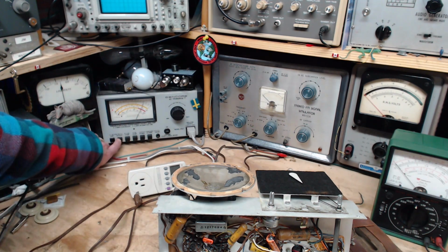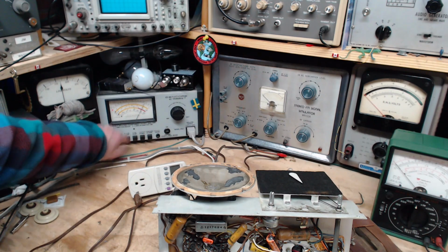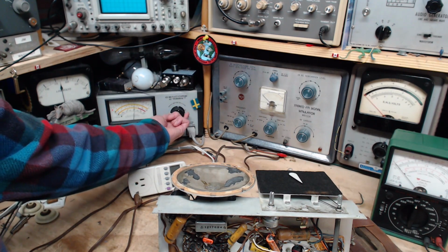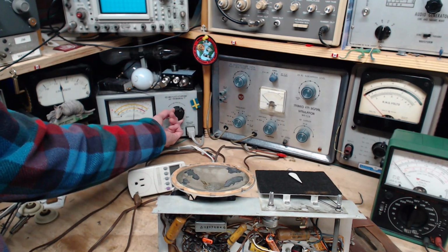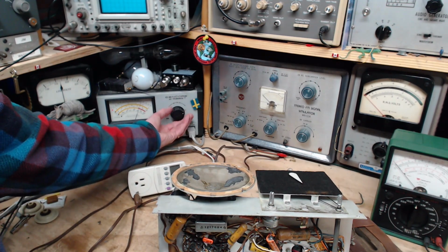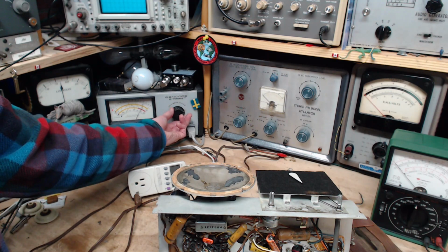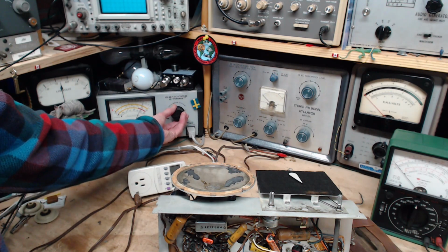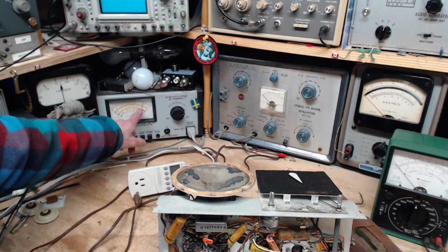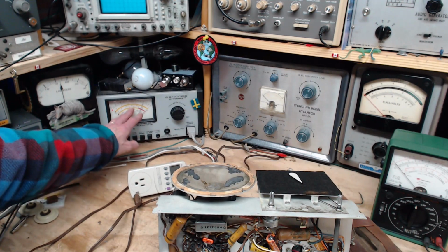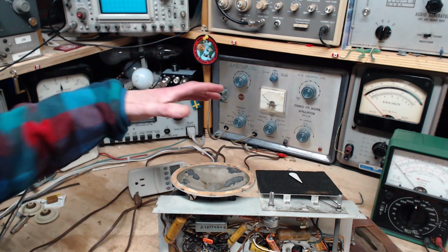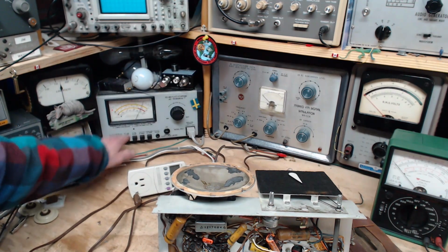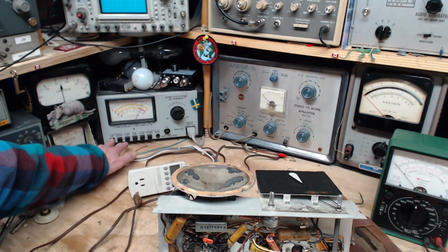Here, this is the output. The output is controlled with this knob, so you can crank it way down and start your device with 40 volts if you want, or you can start it with higher. You can turn it higher if you want, but I usually leave it set so 120 is coming out. So you can see how you can have a low input voltage, 110 volts, and you can still get 120 coming out of this if you really want to get that voltage. Where would you get it from otherwise? You need something like this.